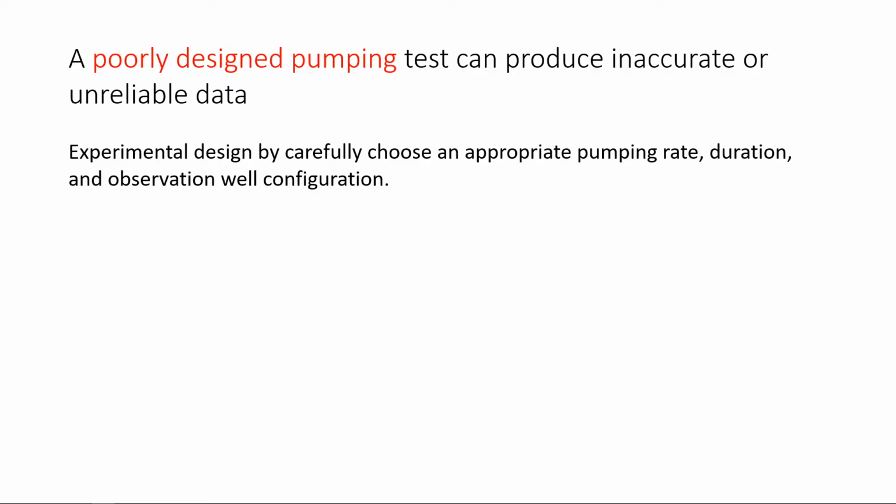The duration of the pumping test: if it's too short, the water level may not have time to stabilize, and then you cannot take accurate measurements. You see, for all of the pumping tests we conducted, we were pumping for at least a couple of hours, like 2 or 3 hours. If it's too long, you might already reach the stabilization phase and you'll just not be getting any new information.